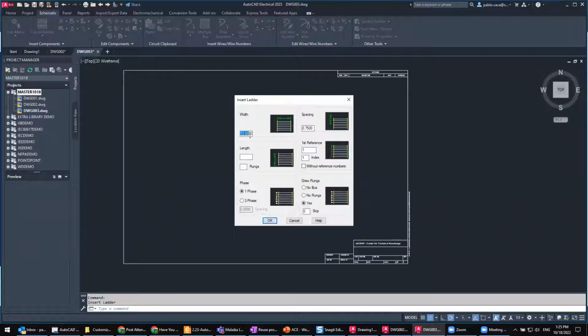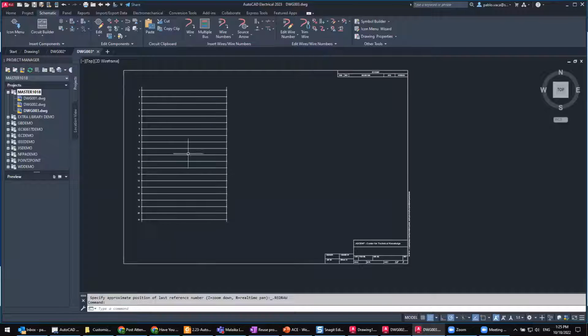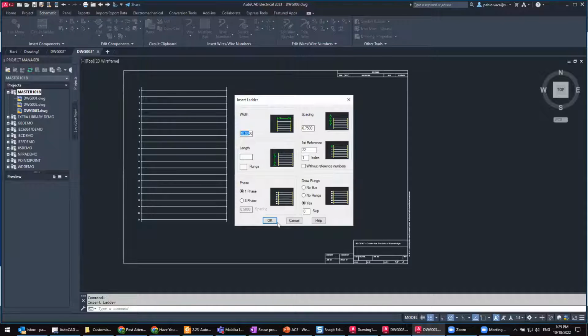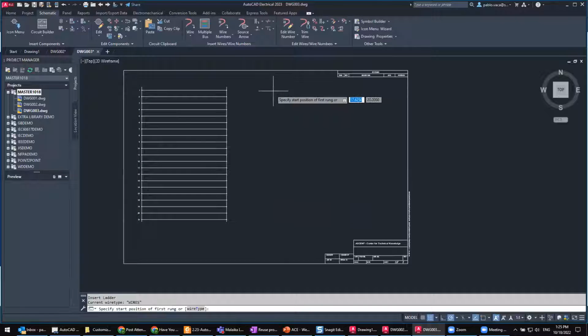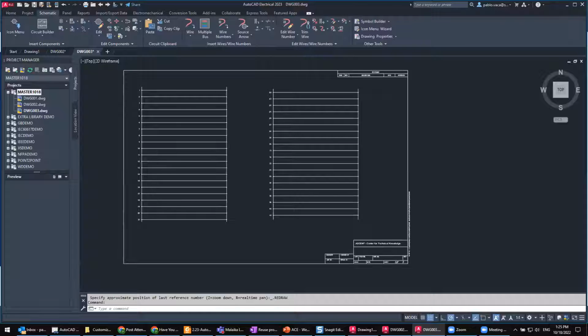So you can see from here, the width that I preset before is now going to be 10. So from here, I'm just going to go in here, and you can see it's always going to be 10 when I start a ladder. I select it over here. It's always going to be 10. So this way, the designers do not have to guess what's the specific width that I need to work with. So this way, you start building the most commonly used design schematics that you use.